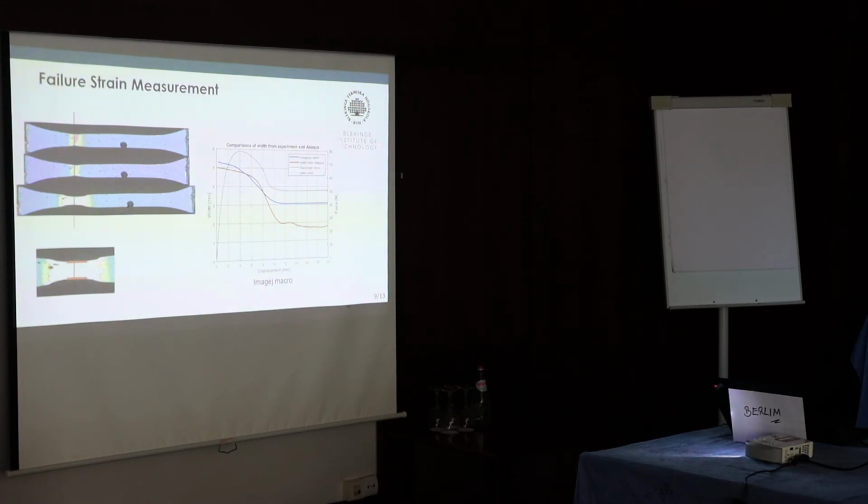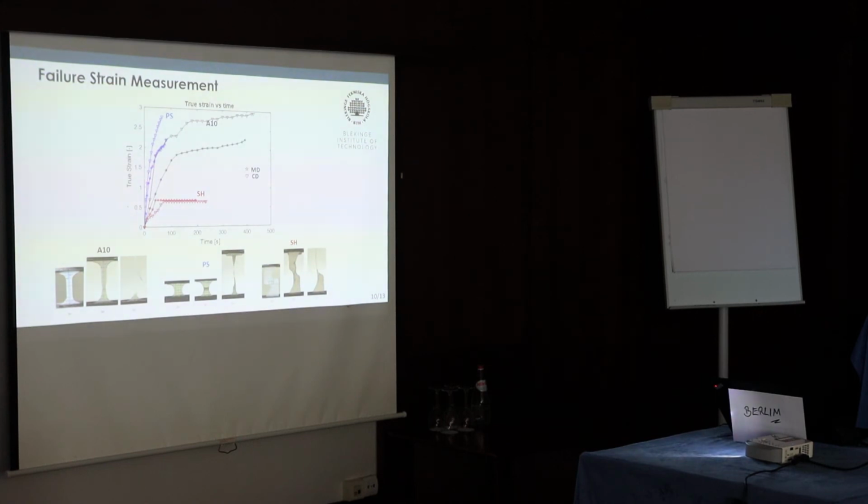Basically you have two lines, and if you write a macro, it can track those lines, and from there you can get the strain. It first has to be calibrated for how many pixels per length. That's probably standard. For example, here the width has been measured. So finally, these are the curves that we obtained using image processing software.